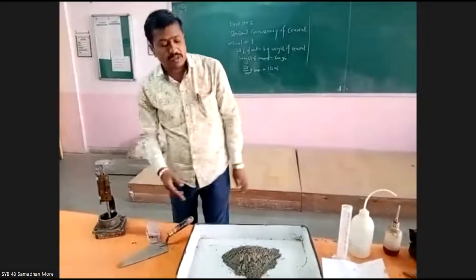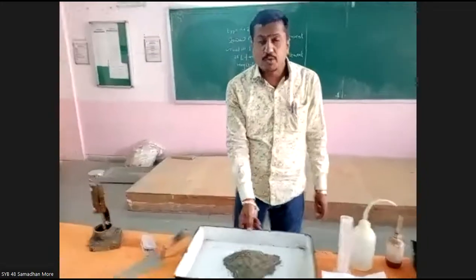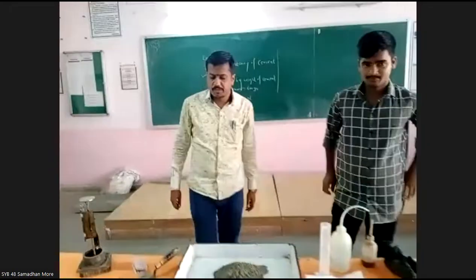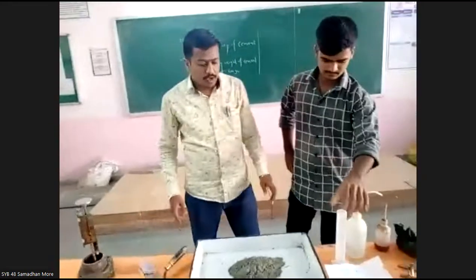Okay. Now we have taken 400 gram of cement, and now we are going to mix it. We are going to prepare the good workable paste within 3 to 5 minutes. Within 3 to 5 minutes, our paste must be ready. Okay. Now I will prepare the paste.